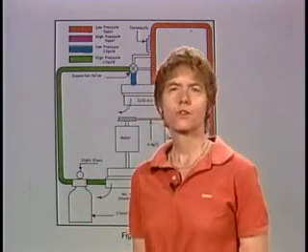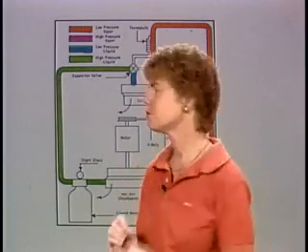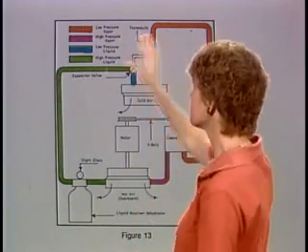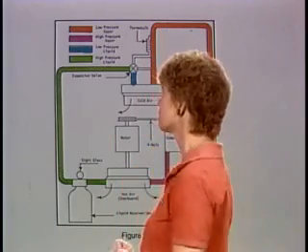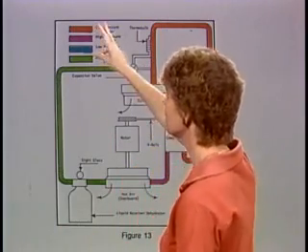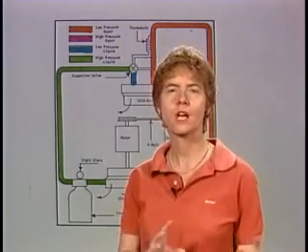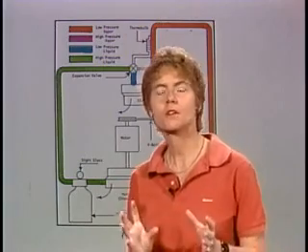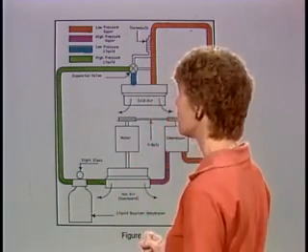And it's very useful even for questions where they do not specifically refer you to it, because the schematic tells you about what's going on and what's happening to the Freon as it moves through the system. And notice there's a key in the upper left corner. Now, the FAA keyed it just with different types of lines and hatchings, but we colorized it in order to help make it a little bit more readable as we talk about it.